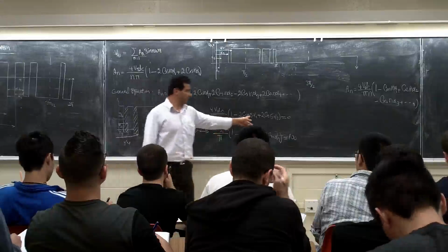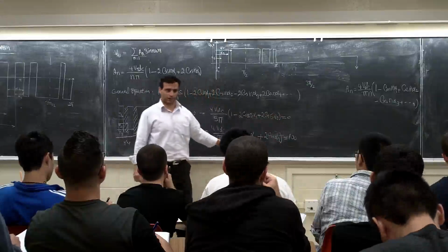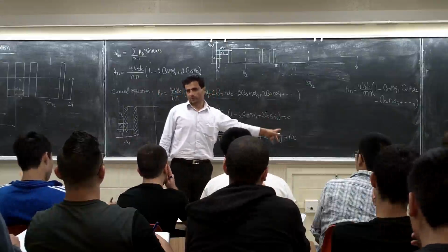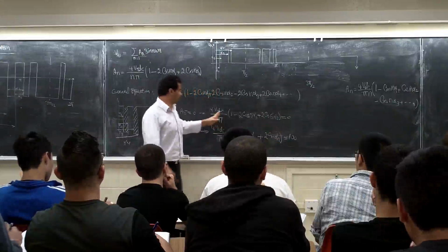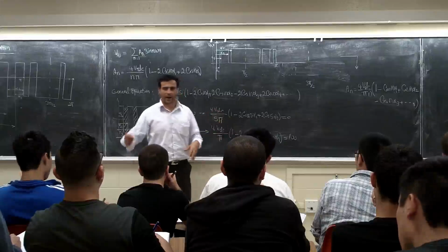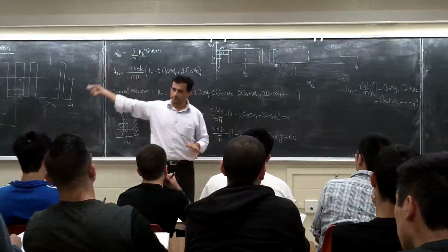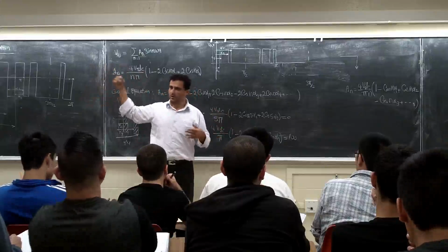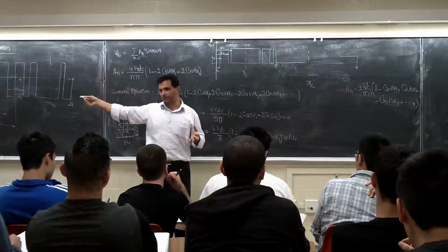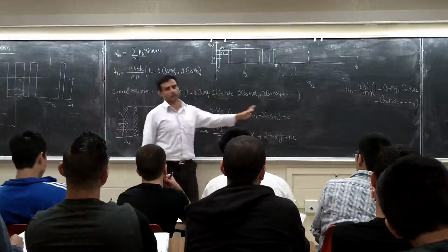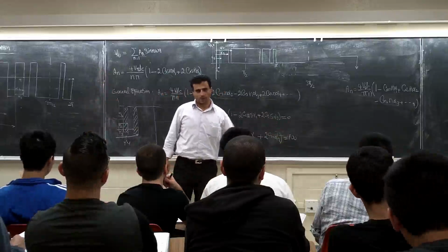Now basically, if you solve these two nonlinear equations, you will figure out alpha 1 and alpha 2. If you select alpha 1, alpha 2 like that, with, for example, a 200 volt DC bus given, you are going to have no third harmonic, because it's three phase, no harmonic number 5, because we set that one to be 0, and for example 100 for the first harmonic.